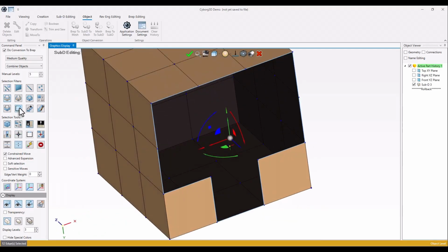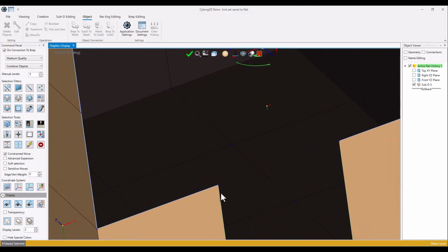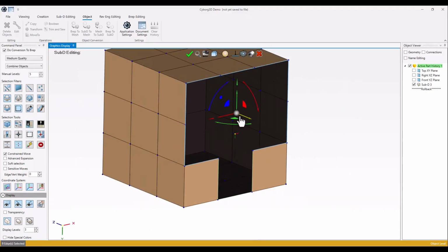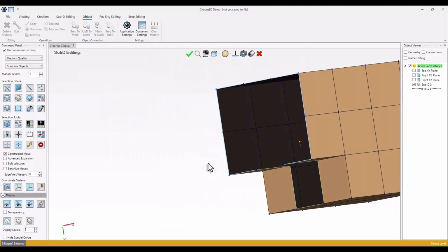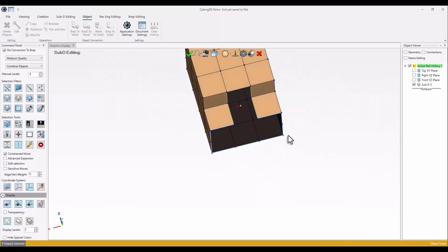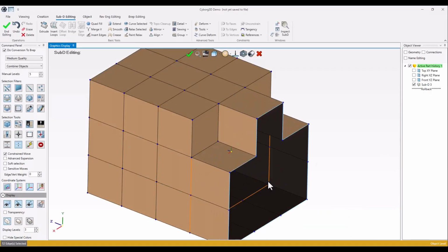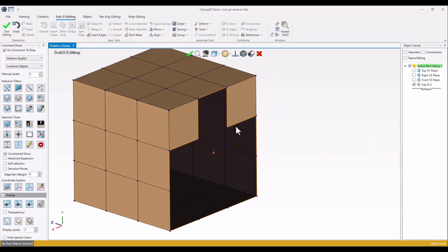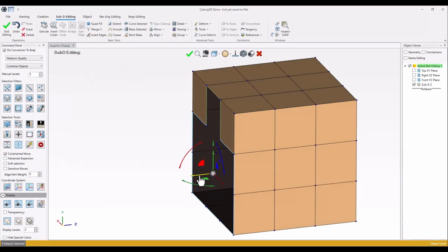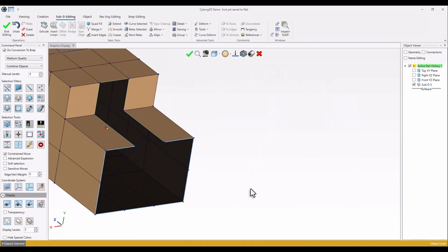And if I set stop at corners, you select to the corners only, so you can just extrude it like that if you want from this side, and you don't have to select the full loop. So it's preventing it from getting the full loop. I've been able to select only this area.